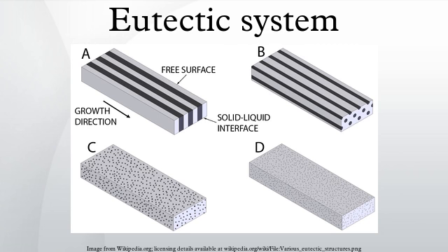Types. Alloys. Eutectic alloys have two or more materials and have a eutectic composition. When a non-eutectic alloy solidifies, its components solidify at different temperatures, exhibiting a plastic melting range. Conversely, when a well-mixed eutectic alloy melts, it does so at a single, sharp temperature. The various phase transformations that occur during the solidification of a particular alloy composition can be understood by drawing a vertical line from the liquid phase to the solid phase on the phase diagram for that alloy.